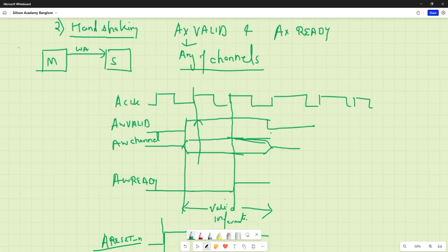With the help of the write address channel, the master tells the slave what is the length of my data, what is the address that I am targeting for write, and many such informations. After that the write data transaction will happen.